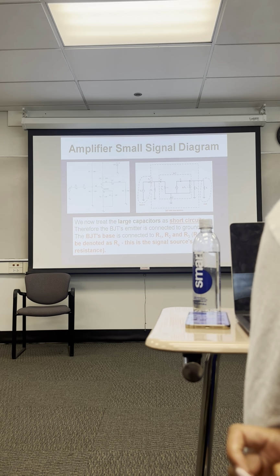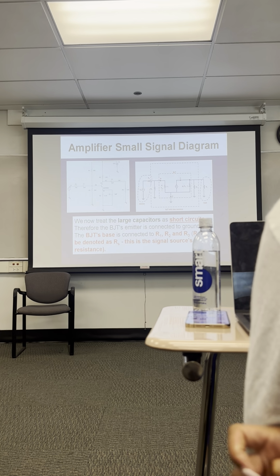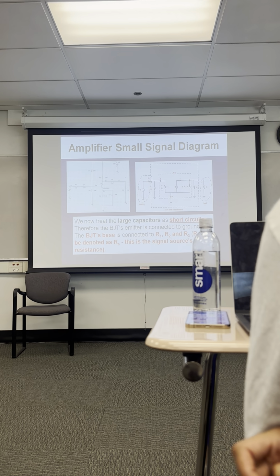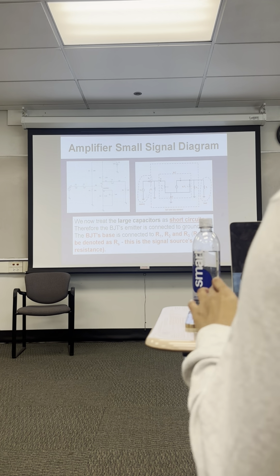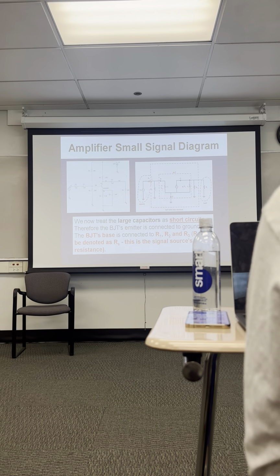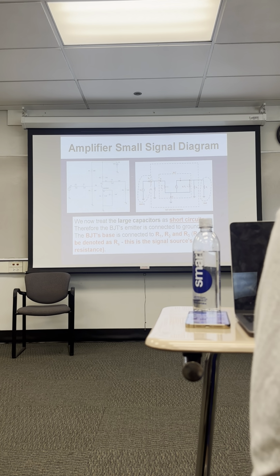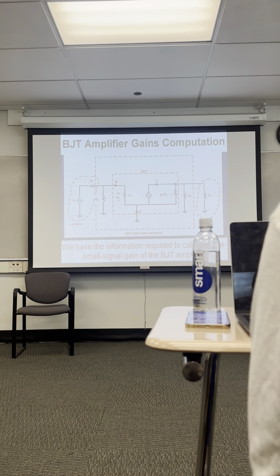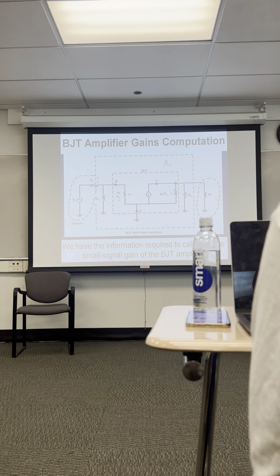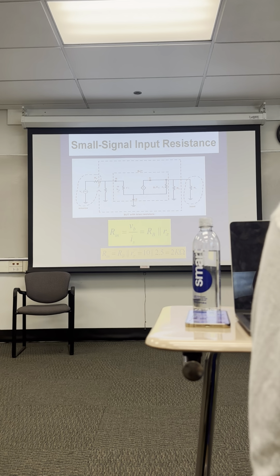So this is basically a model of this transistor. We still would probably build a breadboard to check the model, but here we can assume that in replacement of doing a breadboard, as long as we have the model, we can calculate the gain of this amplifier. So now we can calculate A sub v, and then we can calculate R sub in of the transistor. So R_in is R_B in parallel with r pi.